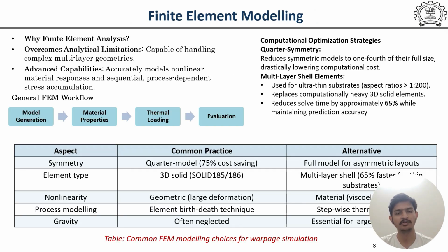Finite element analysis, or FEM, is our primary workhorse because it overcomes those analytical limitations. It handles complex geometries, nonlinear viscoelastic materials, and sequential manufacturing steps. The workflow is meticulous. We build a 3D model of the layer stack, assign temperature-dependent material properties, apply thermal profiles that replicate the exact factory heating and cooling cycles, and solve for equilibrium deformation at every step. Because this requires massive computation power, we use two major optimization techniques.